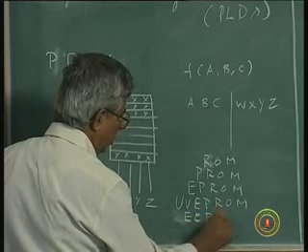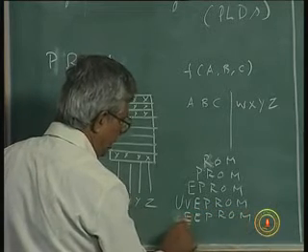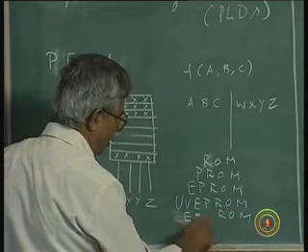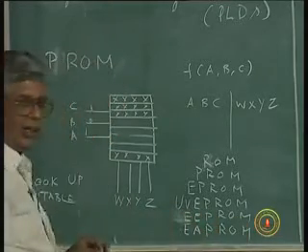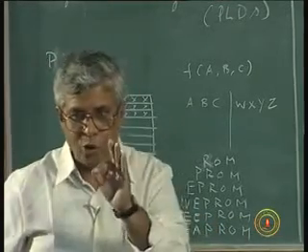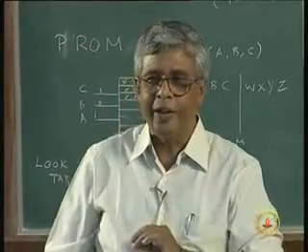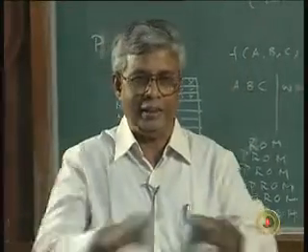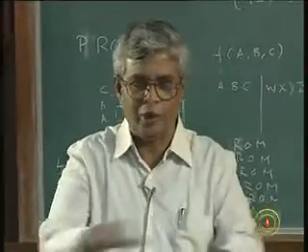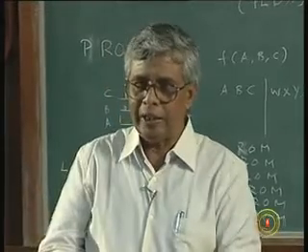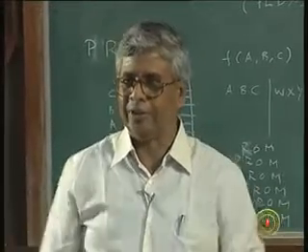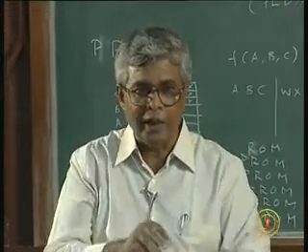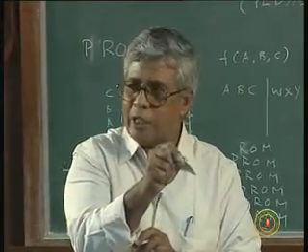Electrically erasable programmable. There's one other technology called electrically alterable programmable memory. What is the difference between electrically erasable and electrically alterable? Erasing means you erase the whole thing like a slate; I have a slate in which I erase it and start all over again. Ultraviolet rays will erase the whole thing. Electrically erasable, I can erase the whole thing, whereas electrically alterable, I can selectively go and change, alter.